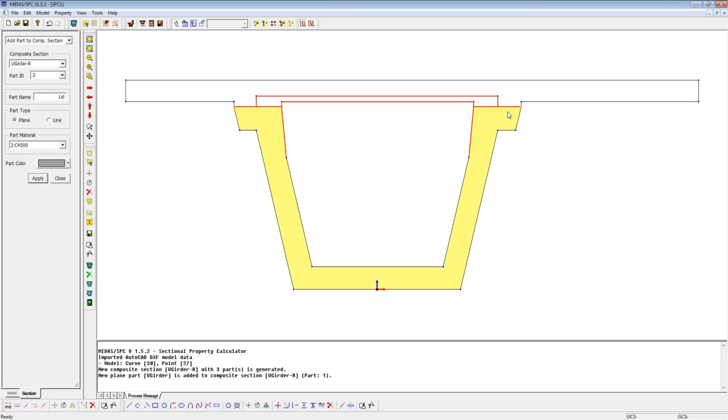and I'll just select the boundaries, and I'll unselect the members that I don't need, and I'm just pressing the control button and clicking on the members to unselect it, and then I'll say apply. And then I'll define the third part of this section, and I'll call it deck, and the material property remains the same, but let me use a different color so that you can notice the difference. And I just press the control button and quickly select the sections.